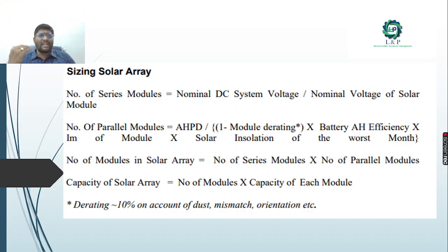Okay, because there are certain days when the production might be good, and certain days when the production might be very less. So always design with higher solar arrays. You can plan the inverter for 1 kVA, but for the solar panels you need to give a higher one, 1.5. Then for the inverter, you can go for 2 kVA. If you want an exact 1 kVA output or a 1.5 kVA output, an exact efficient output, then you need to go for a 2 kVA inverter and have a solar array of around 1.5 kVA. You need to design like this from the starting.